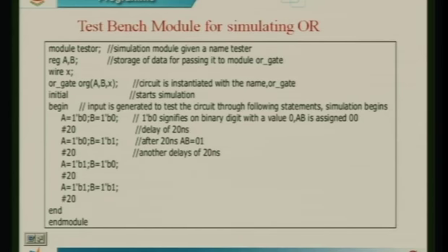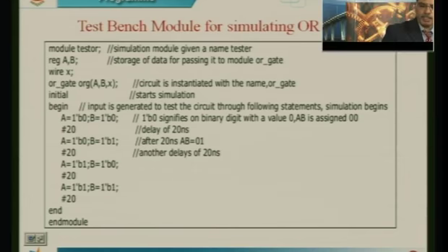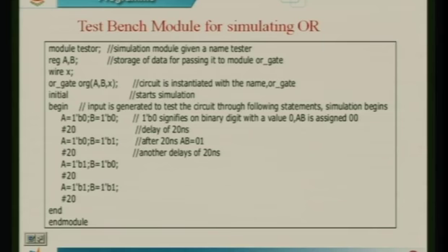So OR gate, which gate you are simulating, it means that it is an OR gate. This is a label that you are given here, like organization, and we have the next syntax called initial. This will tell the simulator that the sequential type of testing will begin, that is called a start of simulation. It is particularly used, like an always statement, to initialize the simulation process.